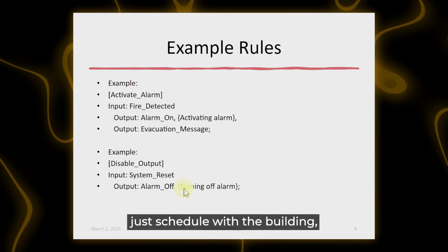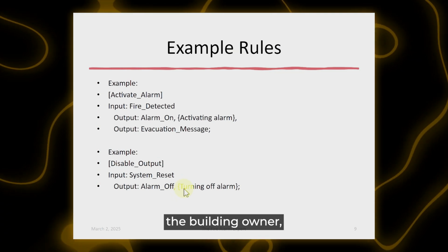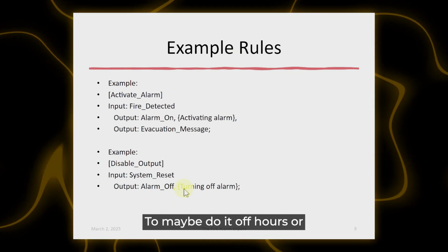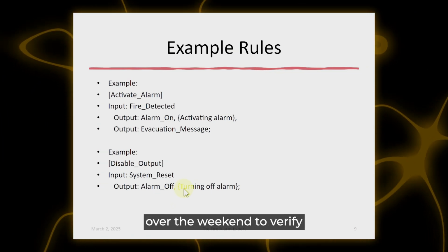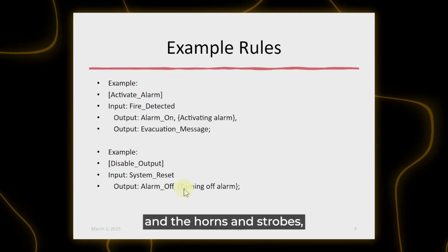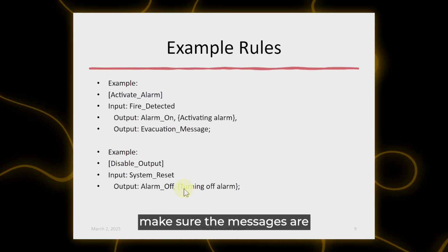And for me to verify the output side, I schedule with the building owner, whomever you have to schedule it with, to maybe do it off hours or over the weekend and verify elevators, fans, and the horns and strobes, or if you're working on the voice system, make sure the messages are there as well.